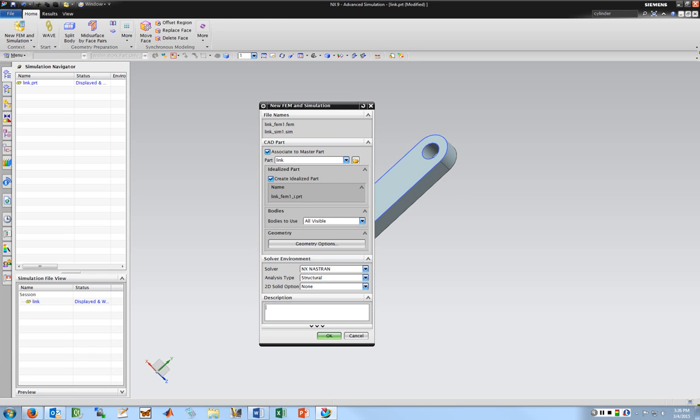You might if you need a different solver. This is just going to use Nastran. You can see the other options here. There's quite a few. A lot of these depend on what licenses you have. Nastran, it's a pretty good one to start with. You can see something about thermal and flow. I don't know exactly what flow it does. Really, this isn't CFD, so you need a completely different application, something like ANSYS Workbench to do CFD. But there's some options here. I know LS-DYNA is for high nonlinear deformations like car crash testing and things like that, but I don't know what the licenses situation is for that. We'll just stick to Nastran.